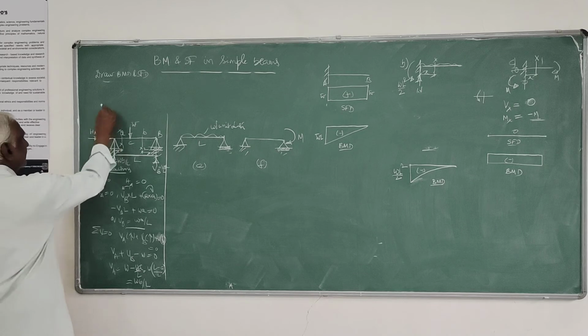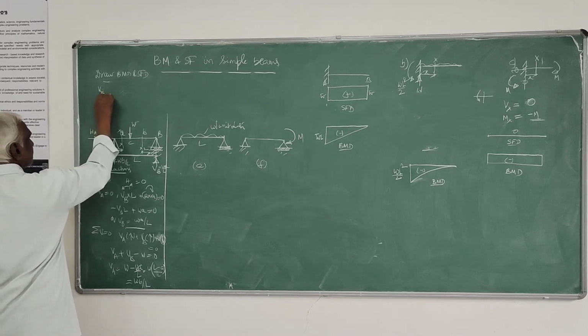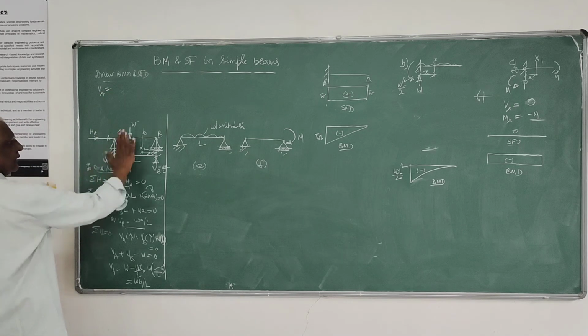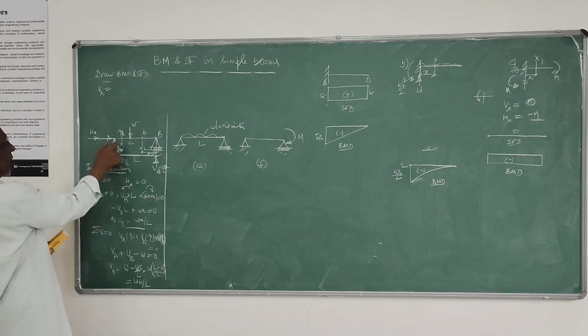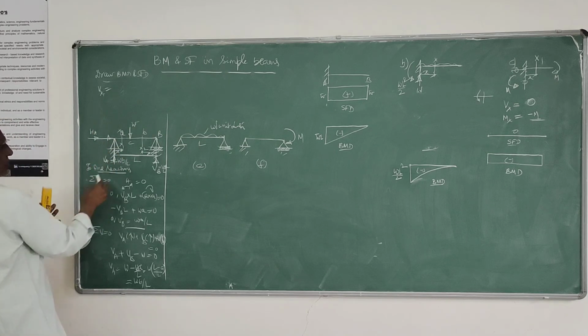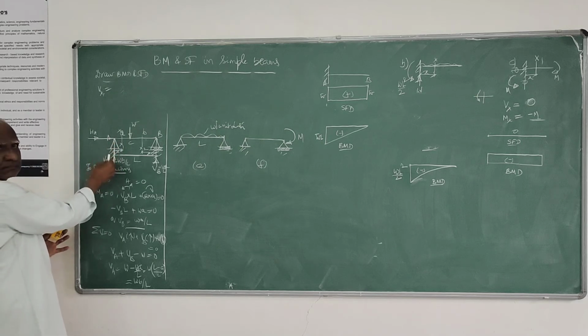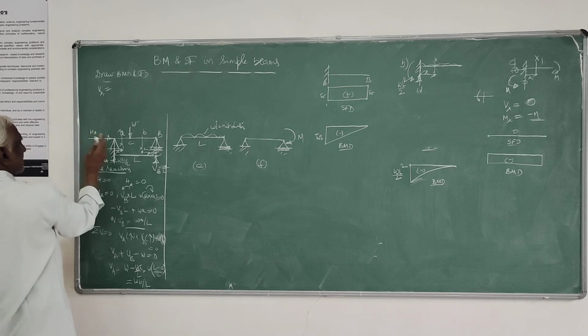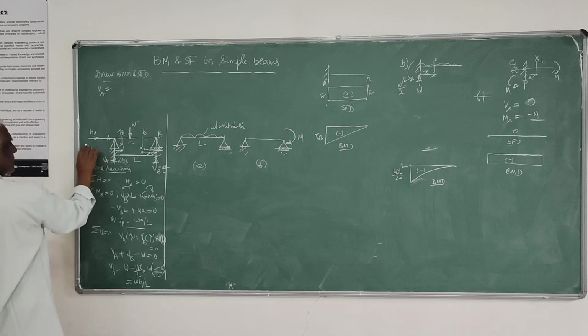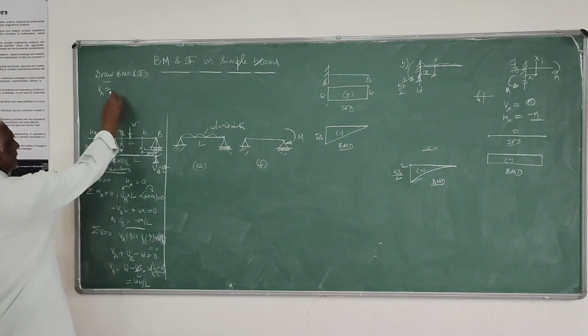So you write the equation for shear force at x1. Take towards left because I am measuring the distance from left. The algebraic sum of all vertical forces is only this. This is horizontal. So it is only acting up towards the left side. It is positive as per our same convention.